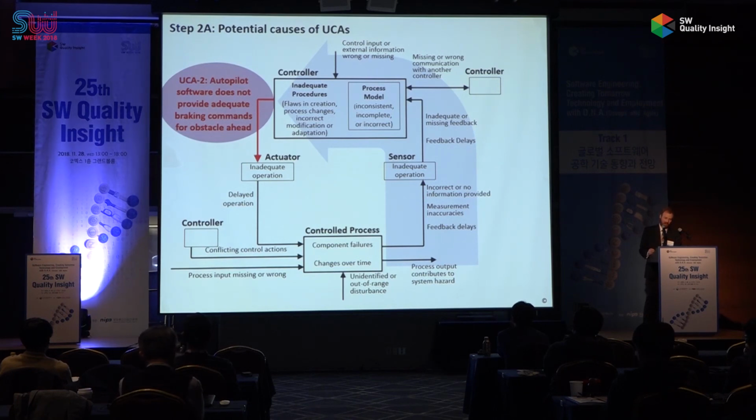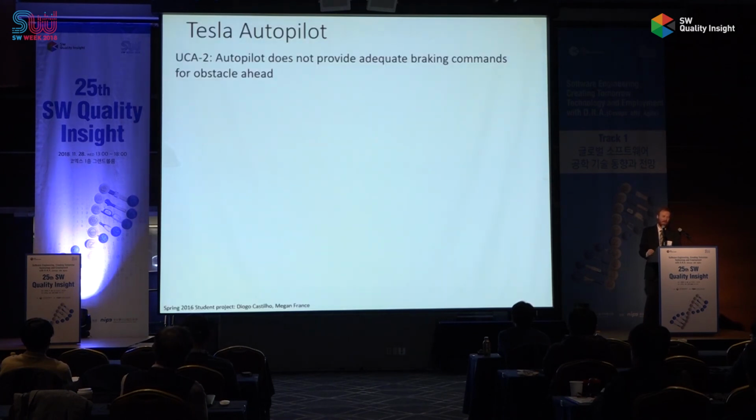There are some failures that can cause this if the sensors fail. But we know that. We can detect failures. What about a non-failure? Well, if another car moves in the way and we can't see the obstacle, obviously we're going to believe there is no obstacle when there is one. And you can identify scenarios just like this, using this reasoning, work backward, and identify the accident before it happens. The students did this. Here are two scenarios they found in just a couple days.